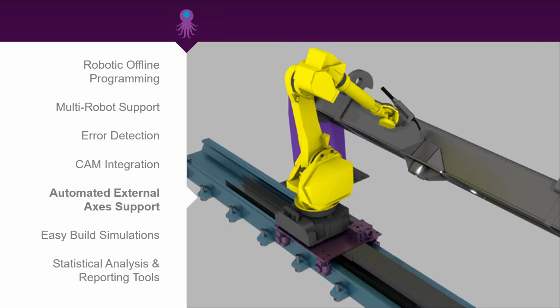Something else that is, I would say, one of the ways that we stand out is how easily we connect our robots into any external axes that you might have inside your cell. So whether that is, I'll actually be showing you something quite similar to what you see here, whether it's a robot on a rail or on a 2 or 3 axis gantry, whether it's operating with a 2 or 3 axis positioner, or in this case a headstock, tailstock, or any combination therein that you can imagine. We're going to generate code that isn't just 6 axis code, it's actually 7, 8, 9, 10, 11 axis code, or however many different axes you have connected to that 6 axis arm. We can support anything I mentioned and more. It really depends on what the project is.